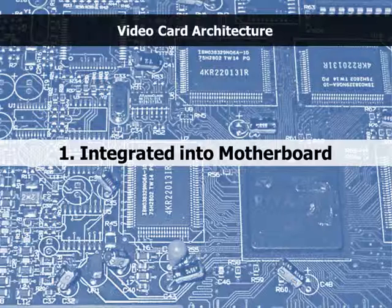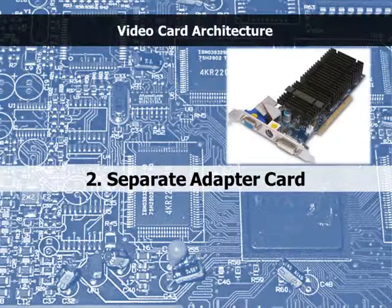Now, when certain functions are integrated into the motherboard, such as video, sound, and so forth, it's sometimes also called onboard. For instance, onboard video or onboard audio and so forth. So you need to keep those both in mind with this particular type of terminology. But there's also the external or separate adapter card, which does fit into the slot and obviously consumes resources. Many times the video that's available on the motherboard may be adequate, but if you want to do really high-powered gaming, you're normally going to have to use a card that actually has those capabilities.